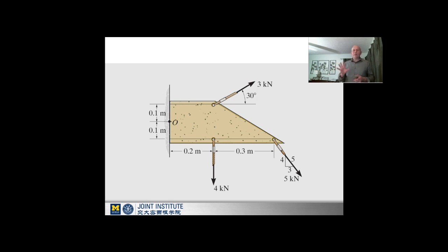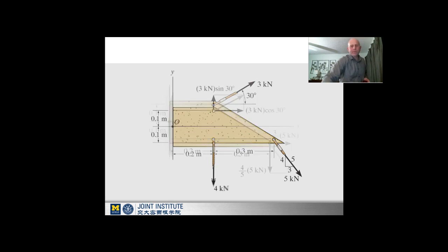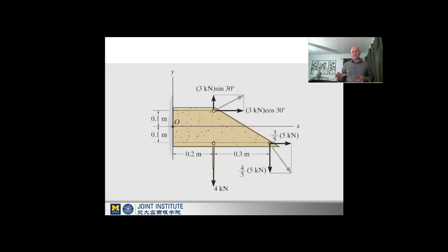Each one, it's relatively easy to calculate its distance, and then we can calculate in rectangular coordinates each of the components of the moment and add them up component by component, the I, J, and/or K components if it was a 2D or 3D problem. So you can see here, it's relatively easy to calculate those distances in rectangular components, but we'd still have to break those forces down to their components to be able to solve that problem quickly and easily.